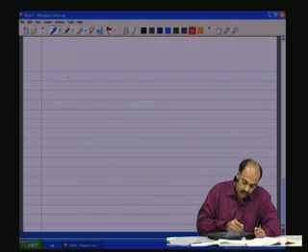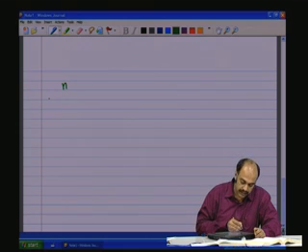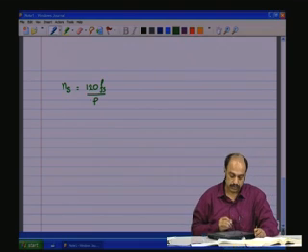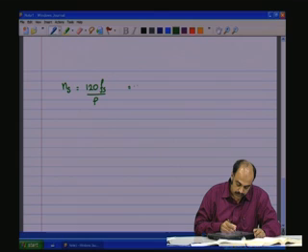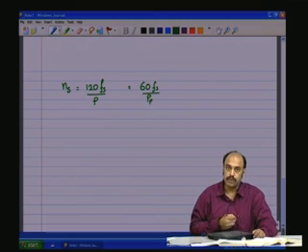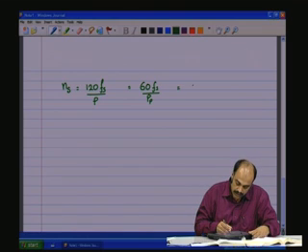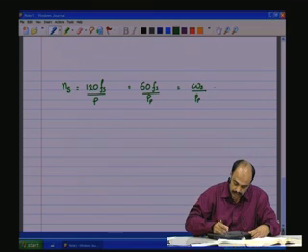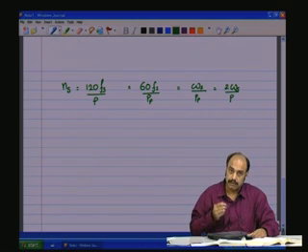So now the rotation of the rotor is in synchronism with the rotating magnetic field, and the speed of the rotating magnetic field is given by, as we saw in the case of the induction motor, 120 Fs by P, where P is the number of poles per phase, or you could say 60 Fs by Pp, the number of pole pairs, or you could say it is omega S by Pp, or equal to 2 omega S by P, where P is the number of poles.